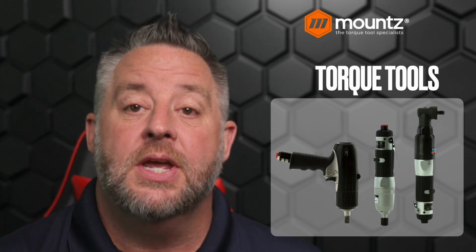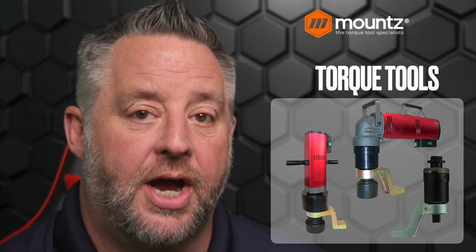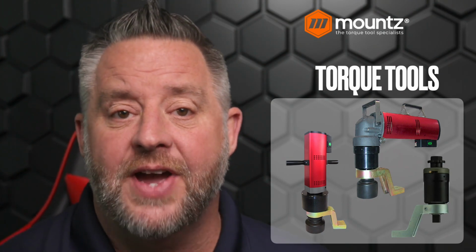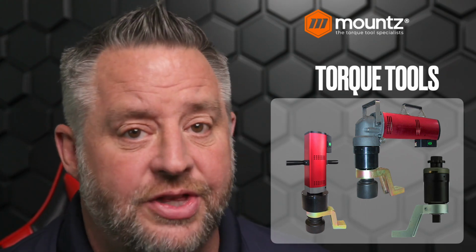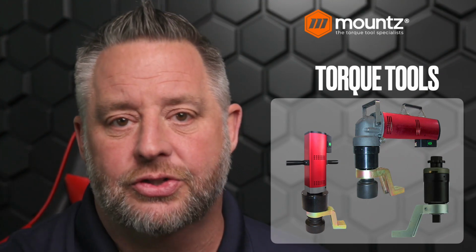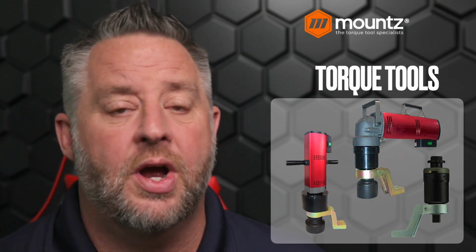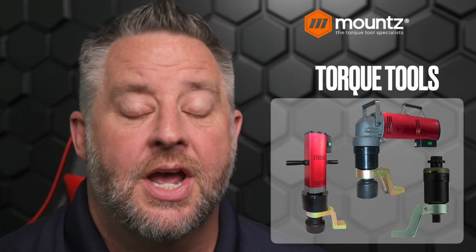And then finally, we have torque multipliers. And so what a torque multiplier allows us to do is to generate torque values in the thousands of foot-pounds, all the way up to 100,000 foot-pounds if we need to. So we basically have an input source that is attached to a gearbox, and that gearbox can have a ratio of 4:1, 12:1, 36:1. It just depends on the amount of torque that we may need.